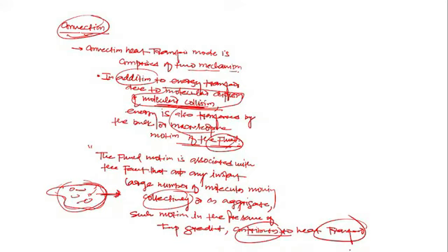Okay, this clear? Now listen. So what I'm saying to you, if molecules are moving collectively, then the collective movement of the molecules also comprises the random motion of molecules. Yes or no? So in this case, a combined mode of heat transfer is taking place. It means here the heat transfer is taking place collectively through bulk motion as well as random motion.